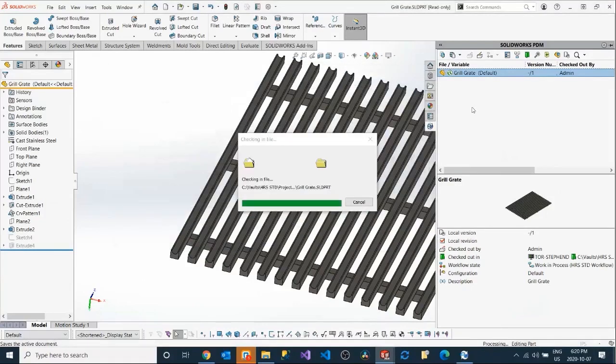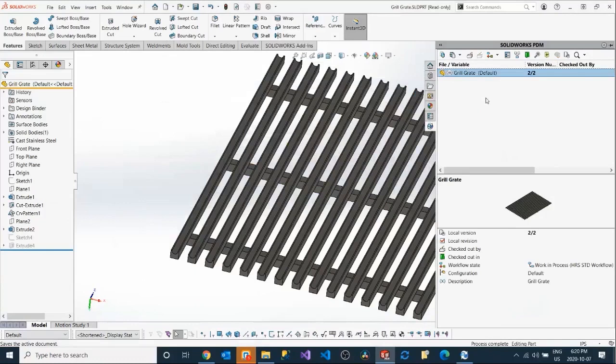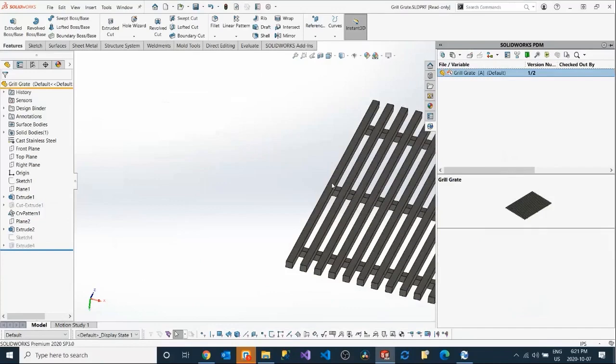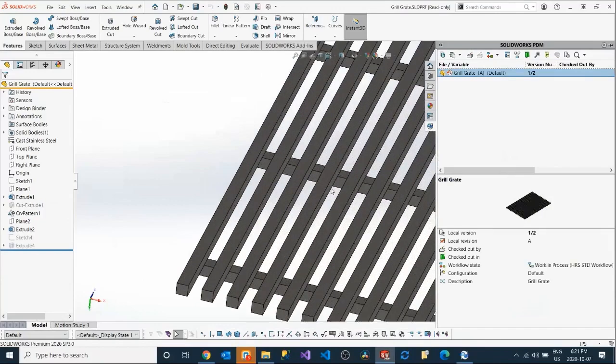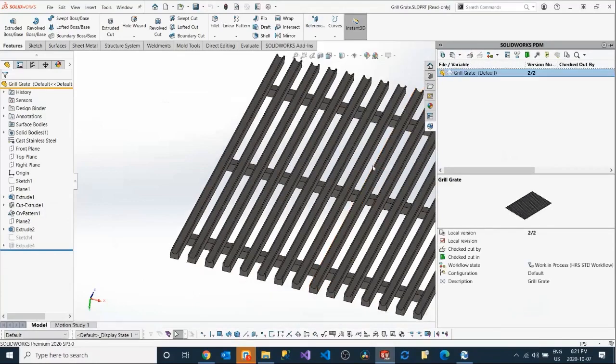But unlike in a Windows environment where we're creating 5 different files for one version of a part, I can access all of those versions of a part from a single file. You might see this version number column in my add-in. I could absolutely pull an earlier version of my file right from SolidWorks and see the initial file that I was working on. And I can go back and forth. You can absolutely do that. So a lot of power here.